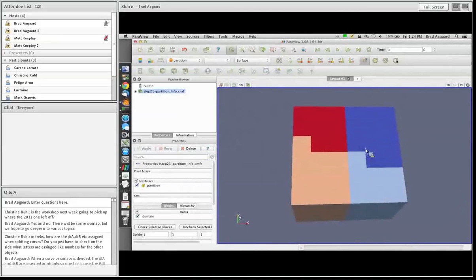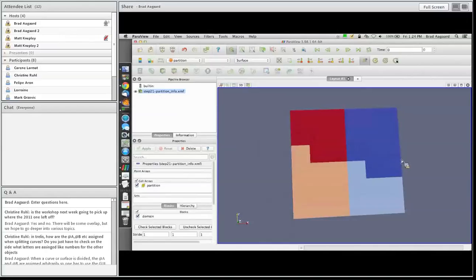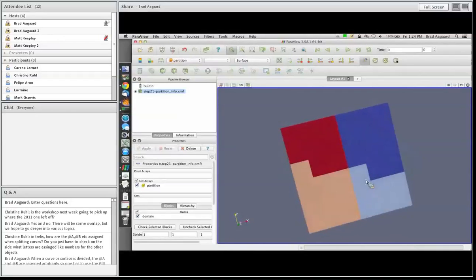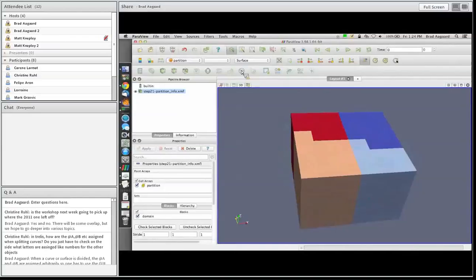So it split once across the fault, and then it did a diagonal, not quite perpendicular. And so there's probably almost no difference between this approach and the absolute optimal approach that would come straight across here. We also have Dirichlet boundary conditions on the ends, and so that can also be affecting our distribution of degrees of freedom, and that can affect our memory balance as well.